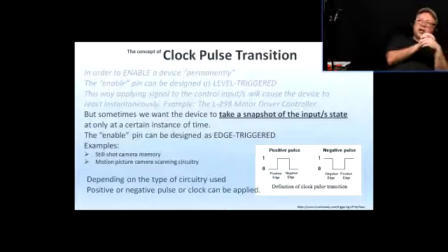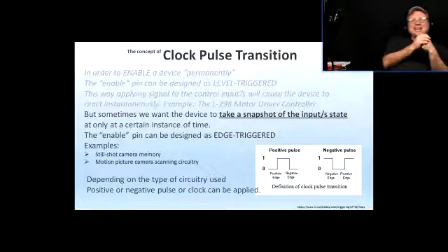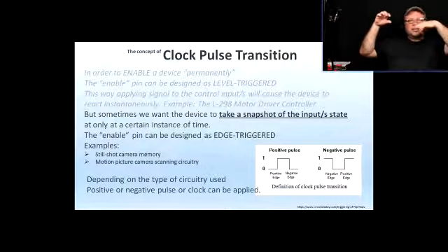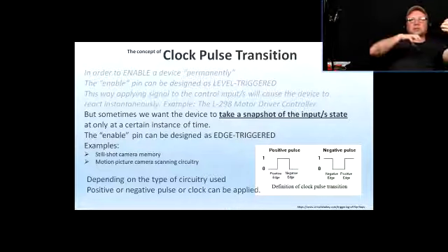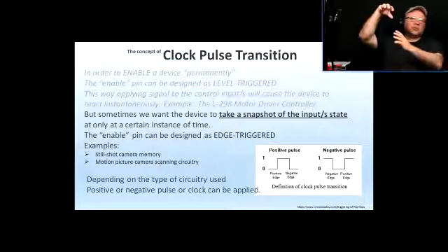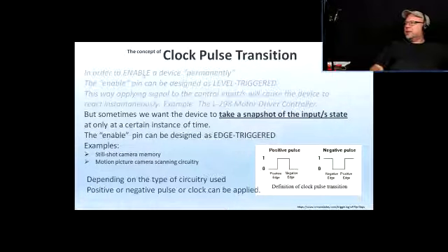And what is a clock? A clock usually is, well, it would be an astable multivibrator. Clock goes all the time. It vibrates. It has a frequency. Whatever the other circuitry is, it might use that clock to perform some operations, and then it might ignore the clock, and things like that, right? So that's why the clock pulse transition here. The clock, well, it goes from one. So as it's an astable multivibrator, it would just go from one to zero all the time at a certain frequency.